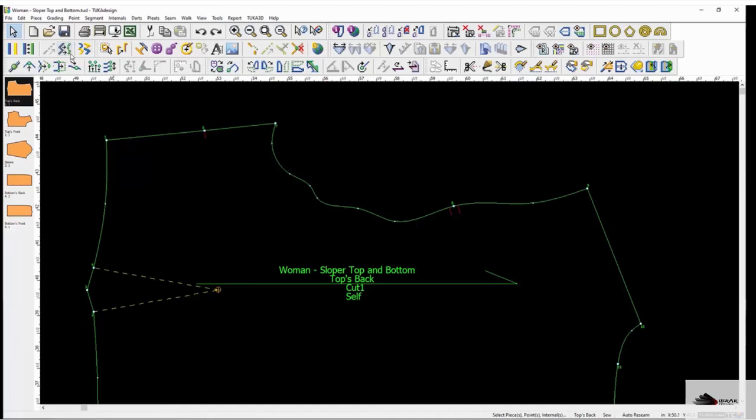Crooked Contour Smooth: select the Smooth tool, then select the segment. The red X's show which points will be included in the new contour. By default, the system shapes the contour using any grade points as anchor points. Use the red line to preview the shape. Click to add or delete points from the contour. Right-click to finish smoothing the contour.